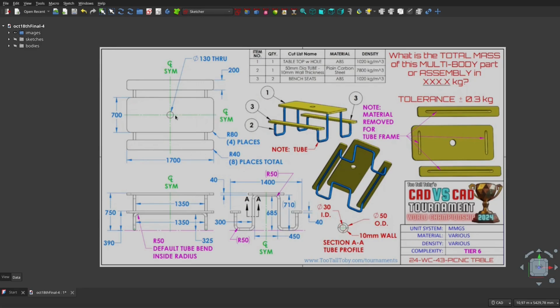To create the tabletop, we'll start by designing its profile and its corresponding path, based on its thickness, to perform an additive sweep. Then, we'll apply a subtractive sweep to create the groove. Once this is done, we'll apply 2 mirror operations. The first gives us half of the table, and applying a second mirror to that result gives us the full tabletop.